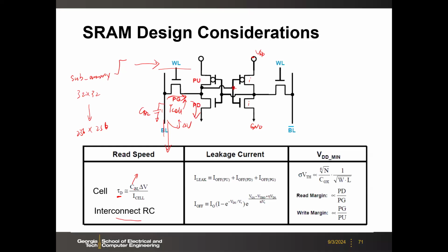For example, if this one is, let's say, 1, and this one is 0, then the NMOS is off. There's no off current through the NMOS. But the PMOS is leaking. So for the PMOS here, VGS is from here and here, and VDS, both are VDD. I mean absolute value. We are talking about absolute value for PMOS because it's all active. So it's all VDD.